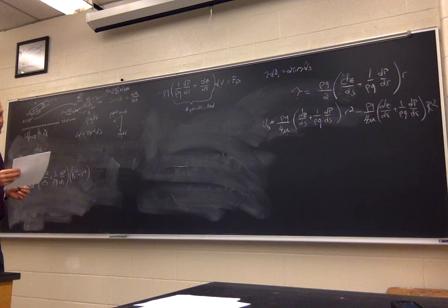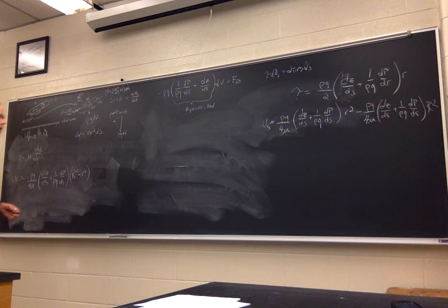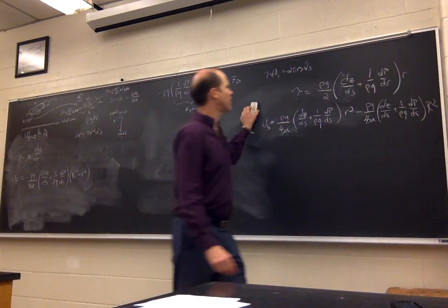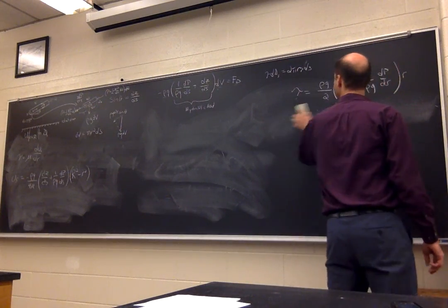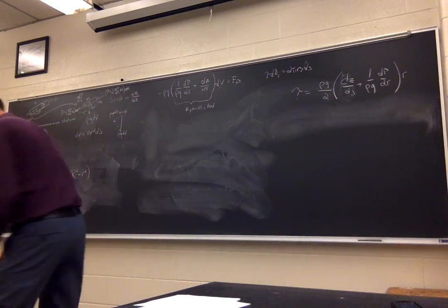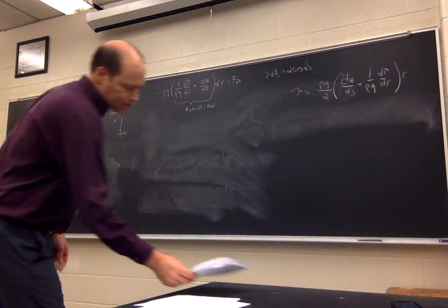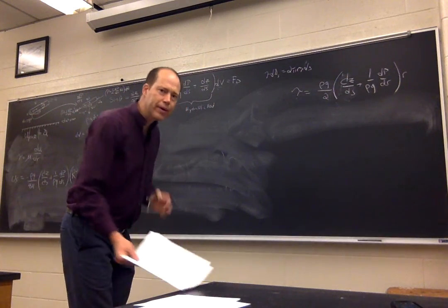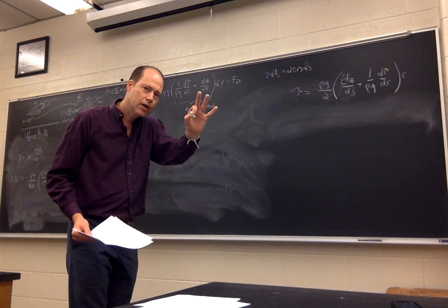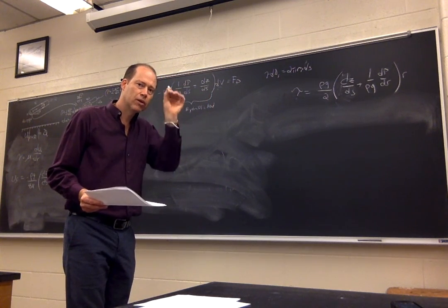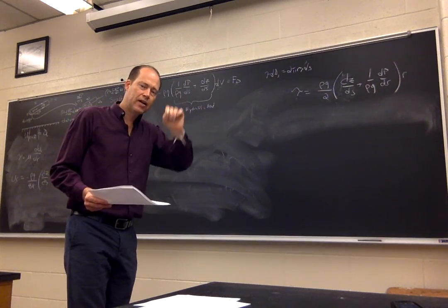If I look at this special case of horizontal flow, this is where now I'm going to calculate a discharge. So let's go back and erase this, and let's look at horizontal flow, because what we'll do now is assess what happens in a system where all we really have are the driving forces related to the pressure gradient, not driving forces related to change in elevation head.